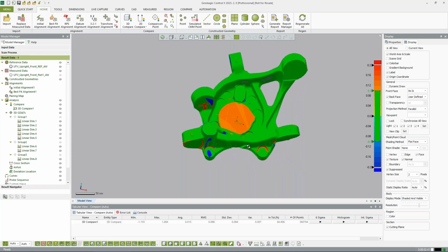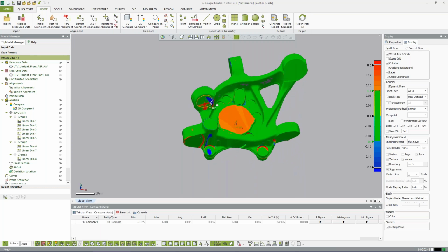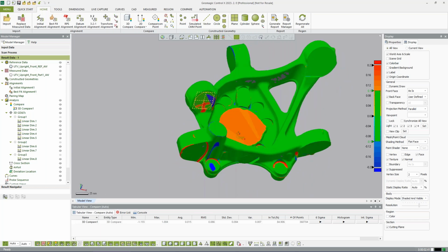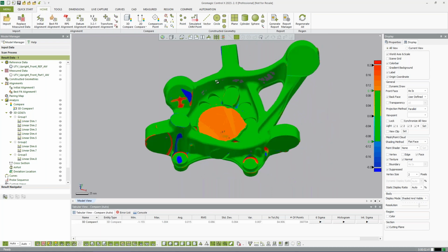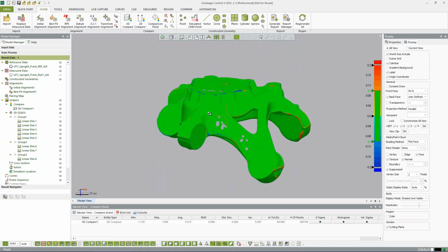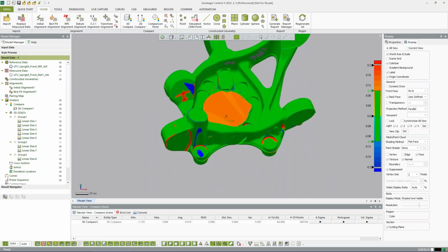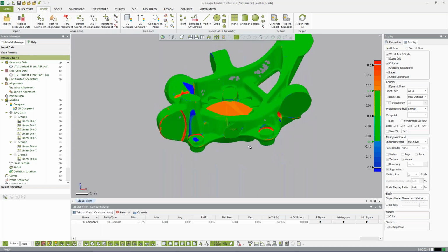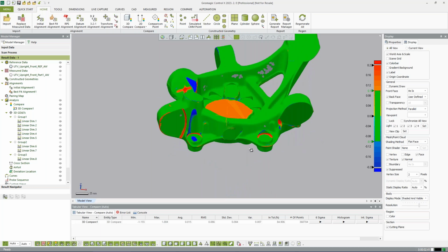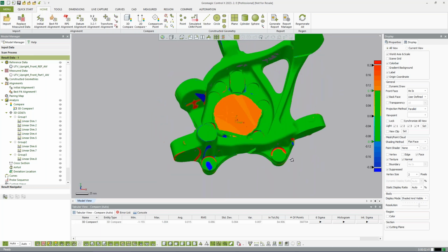So the part's best fit all to itself. We're finding some things like where there was some divot in that casting. And I did fill a bit of hole here that wasn't actually a machined surface though. And then everything else looks pretty good. We can just see some errors around some of the edges and some fill and stuff like that. And then maybe there was a little divot on that face there where something didn't fill all the way and machining didn't clean it up. And then this interface is just high. So we can see that right away, check it.